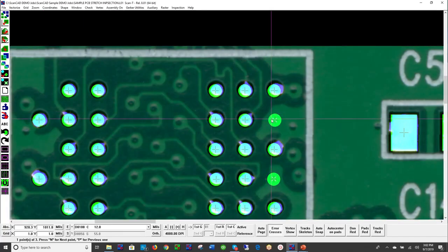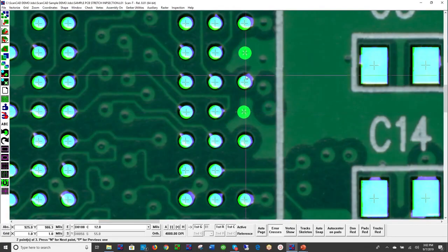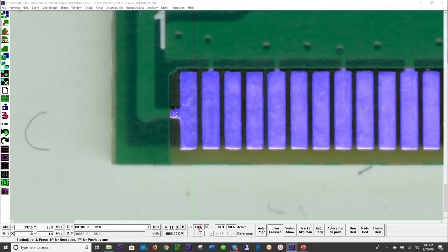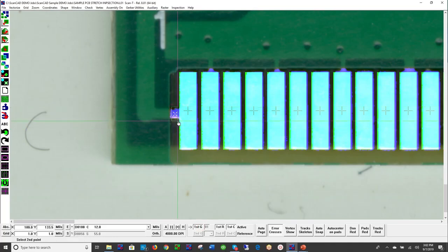And these are those 3 errors we talked about a minute ago. Remember the solder mask that was missing here and here? These 2 errors. And there's some exposed copper right here that could be a serious problem when printing paste, because the solder would actually leak onto here. So they may want to cover this with solder mask.